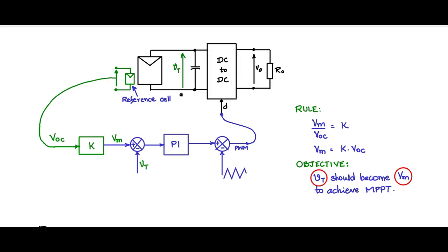Let us discuss the sampling method for performing maximum power point tracking. One can do voltage sampling or even current sampling. One should note that in the case of the reference cell method, a reference cell is used and it is either open circuited or short circuited, depending upon whether Im/ISC is kept constant or Vm/VOC is kept constant.